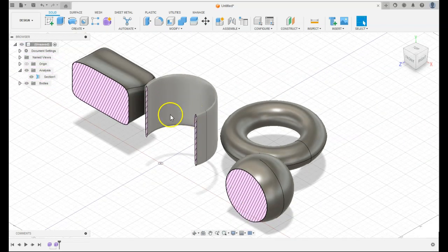Now I misspoke earlier and it's fine. When we're talking about a box, it is going to be filled. So these objects are going to be filled, but when we're talking about a form like a plane or a cylinder, thicken is required in order to get the same effect. An enclosed space will give you a solid body. Okay, so I think that wraps it up from create a form, edit a form, and then thicken a form.